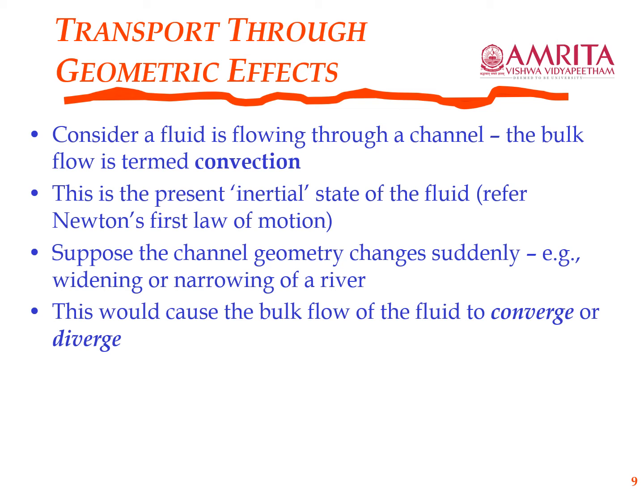Until this widening or narrowing happened, the fluid was all flowing in x direction, so the entire transport was in x direction. All right, now suddenly there is a diverging, and therefore some amount of momentum is now taking a turn towards the y also. So now you can resolve the momentum. If you look at the velocity profile, for example, you can resolve it as having a Vx component and a Vy component also. And this sort of a change means momentum is now transported in the y direction.